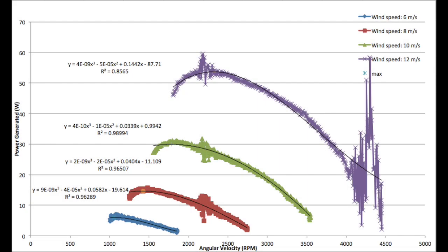During the test, both stall and resonance of the turbine blades were observed. Peaks in power output occur before the onset of stall. This leads us to conclude that maximum efficiency is achieved by operating at the edge of stall.